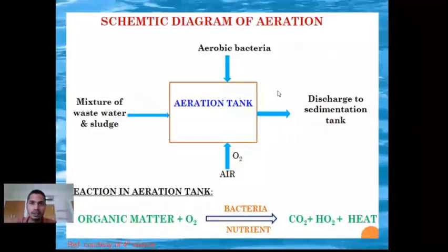Now, this diagram shows you the oxidative digestion, or the aeration lagoon system. In the aeration lagoon, the process is quite simple. You have the mixture of wastewater and sludge. It comes into the aeration tank. You aerate it, and you have activated sludge,